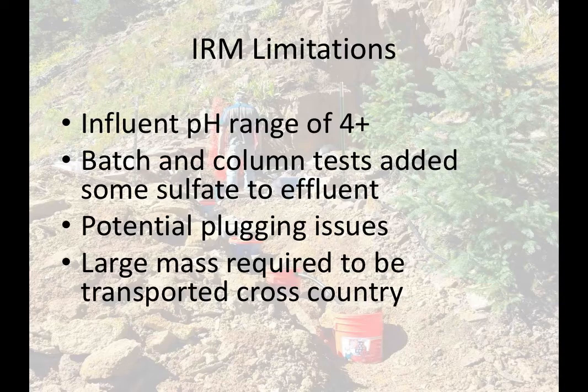There's some of the limitations, the influent pH range. When we tested it on some water that was a little lower, it started actually taking manganese back into solution, which was something we did not want to do. There's a little bit of sulfate that was added. There's some potential plugging issues, which we were looking at solving through some innovative engineering ideas with parallel cells that would, as they plugged, back water up into a head tank and automatically kick into a fresh cell.